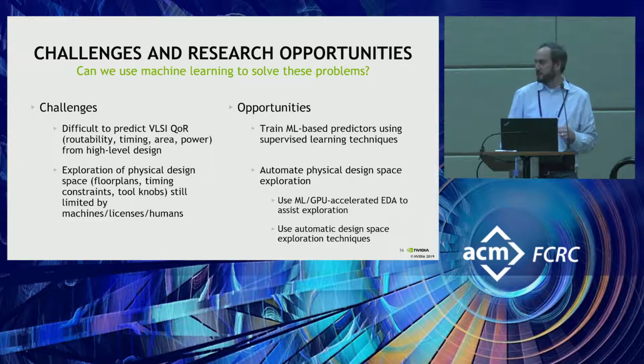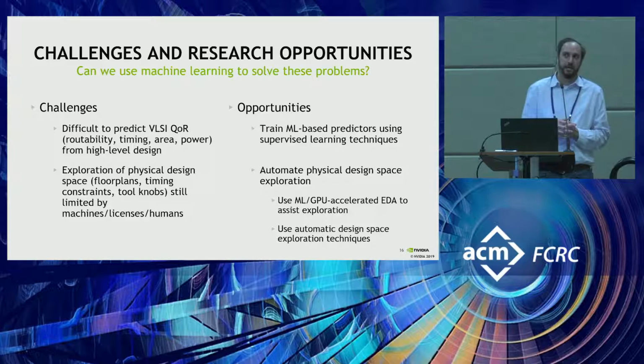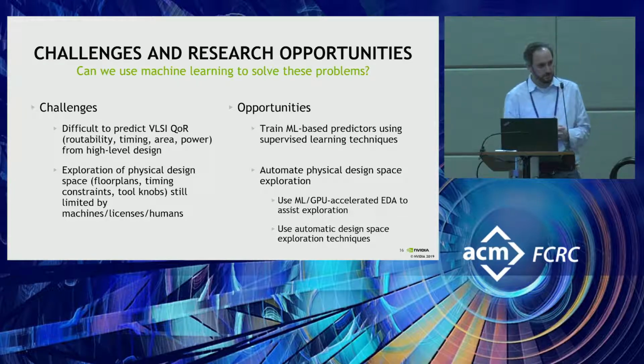First of all, HLS is a tool if you want to give control over hardware scheduling and pipelining to a tool, and you don't want to keep it as a designer. So I would never build a processor core using it, for example. If you want precise control, it's not the right solution.